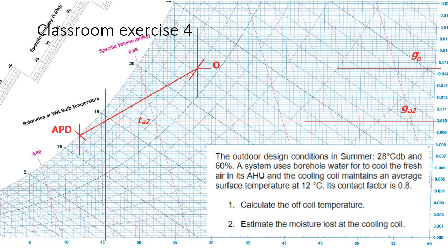If we reduce further to 20 degrees, it's almost 100% saturated. So you can see if in the room there's a surface that has a temperature lower than, let's say, 19 degrees, we'll surely see the surface accumulate droplets. Actually, the condensation happens.